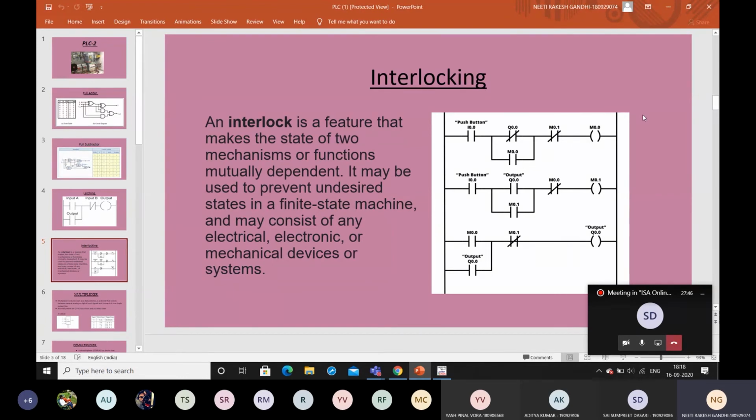Correct. Now when this operation is on, this rung is shut and so is this. I mean, this gate is shut and so is this. So it's a complete circuit either way. Now when I press this push button, I was getting input over here, but both of these are still open, so there's no point, this is not going to get triggered. Okay, so now if I were to open my Q0.0, this circuit becomes a closed circuit.